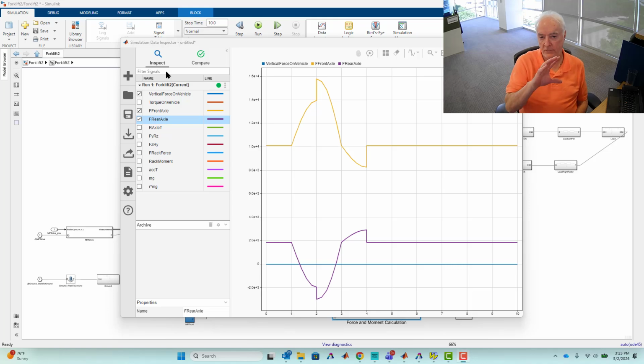Okay, in this video, we're going to use Simulink and this type of analysis to figure out what are acceptable, I'll call them motion plans. Maybe we'll call them trajectories or missions, but it's really how do we move it and operate the forks at the same time. In that example that we constructed very quickly, we can see an important violation, which is that the rear axle is going to carry a negative load, which we know will mean it will tip over.